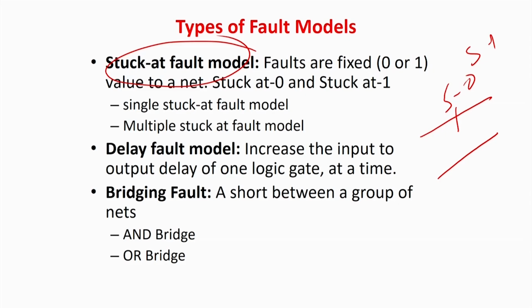In fact, whatever logic I am giving to a line, it should be ported to the other part of the circuit. And it was found statistically, till the last 10 or 15 years, that if a circuit does not have stuck-at faults, the circuit is 99% probable to be working as per the functional specification. So that much guarantee was given. So the stuck-at fault model was a very powerful fault model, and in fact it is also the de facto standard that everybody starts with: the stuck-at faults.